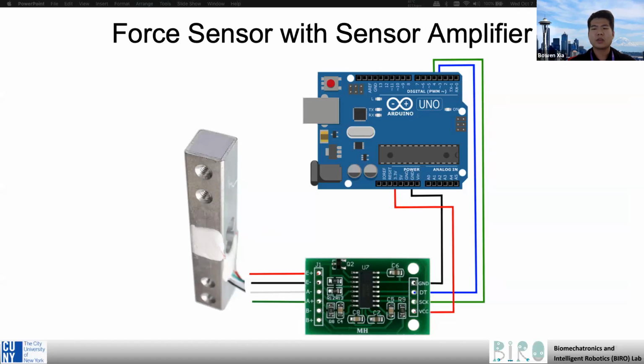So the force sensor is basically a piece of metal that has special electric resistors called strain gauges glued on it. Strain gauges change their electric resistance when they are strained, or being pulled, even by very small strains. When a force is applied to the force sensor, the metal deforms by a very small amount, which is usually not visible to our naked eyes. So the strain gauges change their length along with the metal, which causes a change in their electric resistance.